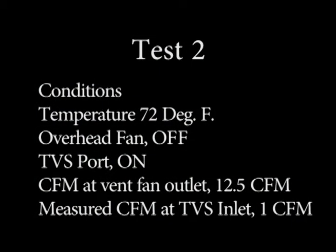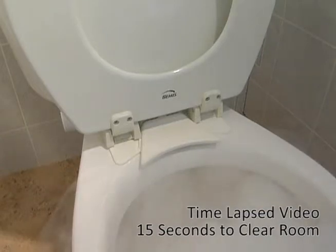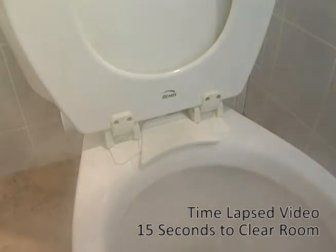Test 2. Test 2 simulated the condition where only the TVS system was connected and operational. The test smoke entered the test chamber through the toilet bowl. It first filled the bottom of the toilet bowl. No visible constituents of the test smoke overflowed the toilet bowl. Injection of smoke was then stopped. After 15 seconds of running the fan after suspension of smoke injection, no smoke was visible in the test chamber or the toilet bowl.